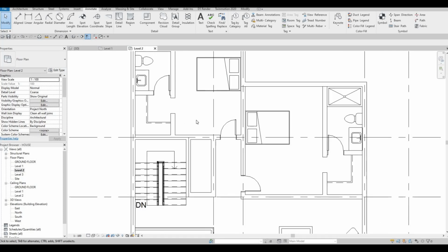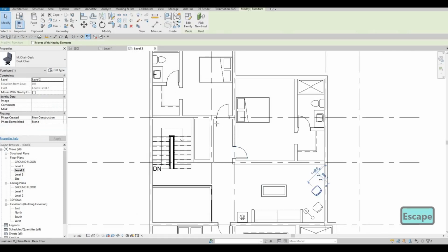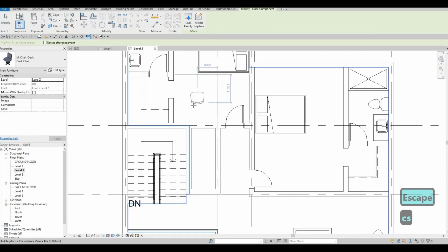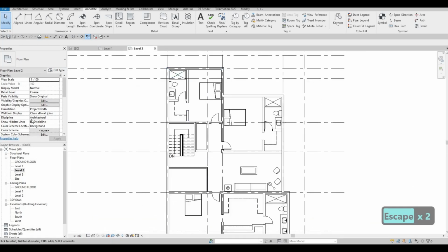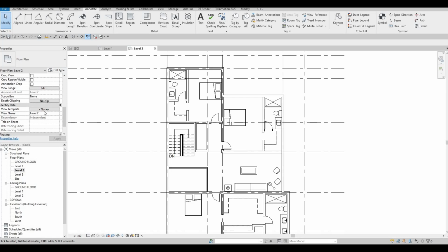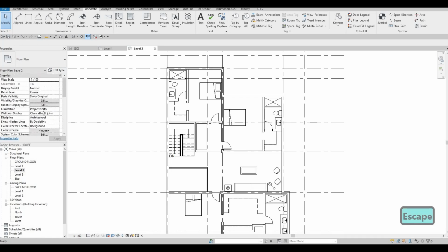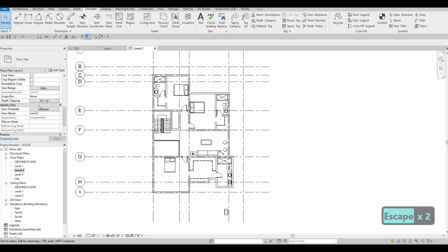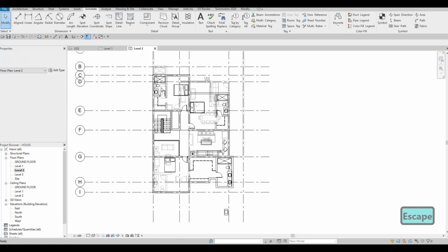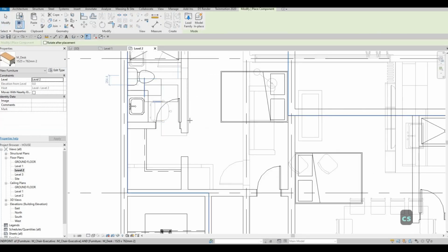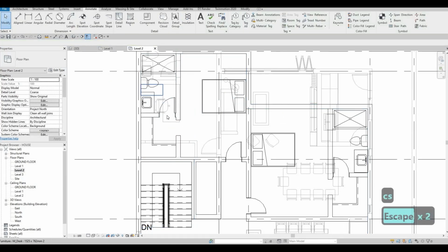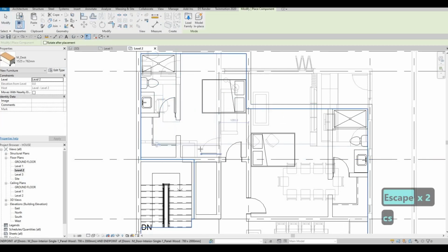We could have some seating here as well if we want to, or we could have a desk as well. So either way, you can have a desk here. I think it's better if we show, because we already added a desk. So just go to underlay and then choose level 1, and then let's add the desk like that right here, or this bigger desk onto this area.